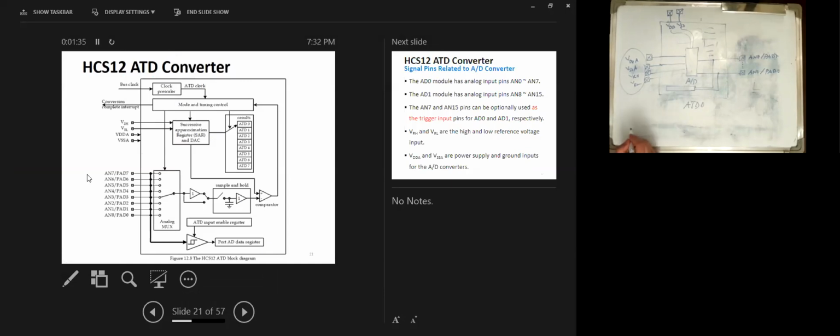Imagine like this. At this moment, imagine that you are using two channels. Let's first take one channel. You are taking samples from one channel. So you have some acquisition time, then you have some conversion time. So this is for sample 1 from channel 1. Then you can take sample 2 from channel 1. So basically this is your sampling period, right? This is your sampling period, and accordingly you know your sampling frequency.